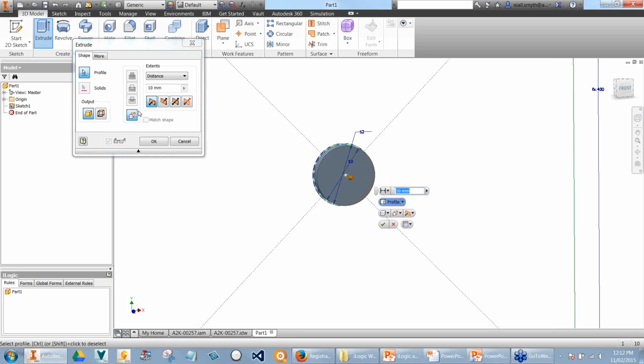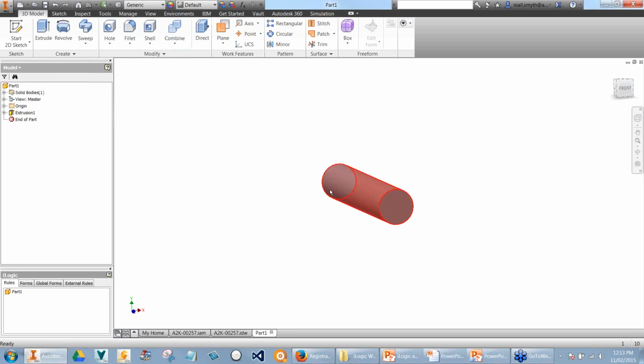To create a solid body, when we see the extrusion tab pop up, there's a little button here that I'm highlighting. That's to turn our extrusion into a solid body. When I press that, I can create another parameter again, and say length equals maybe 300. And you can see that I've created an extrusion that's 300 mil length.